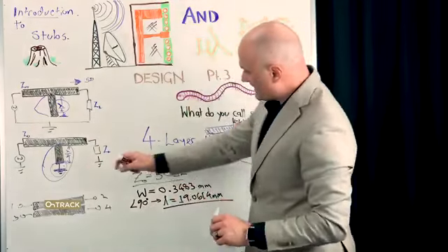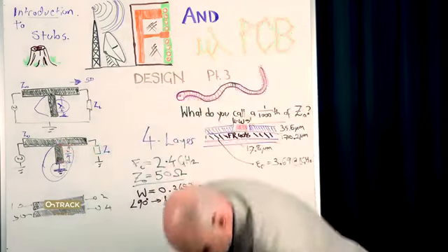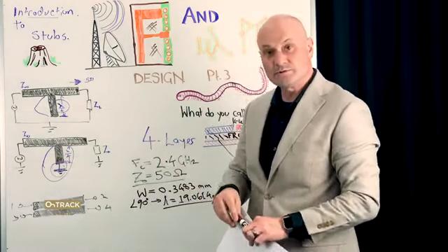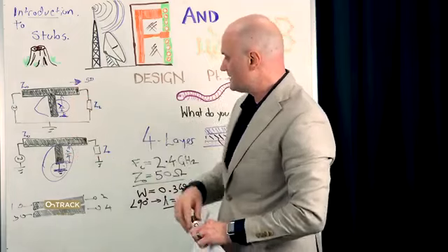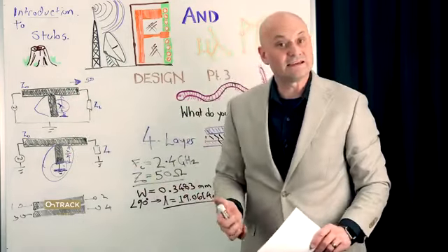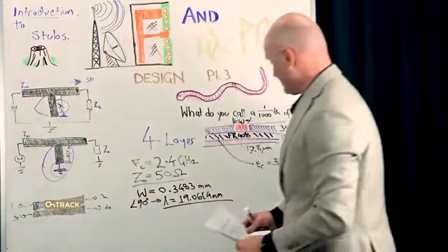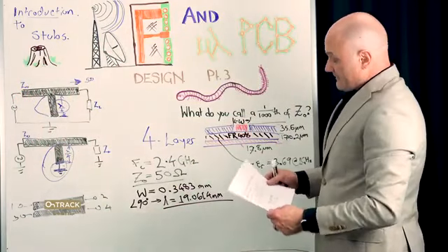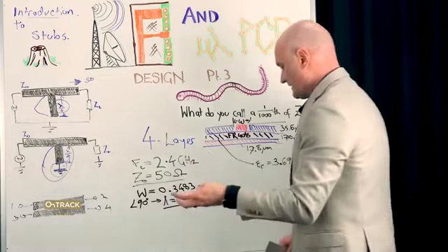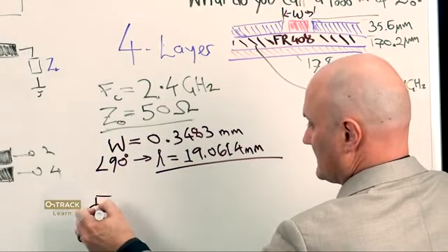And I'm going to be using that to create regions or polygons of that specific length, which I can then copy and paste or put them into a library and place them as parts. And that gives me the ability to start doing interesting things like making bandpass filters. So I have another example of that right here. And that is where we have this kind of structure. So we have our source impedance comes in.